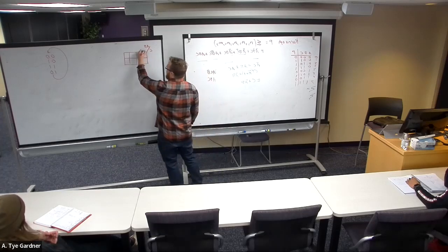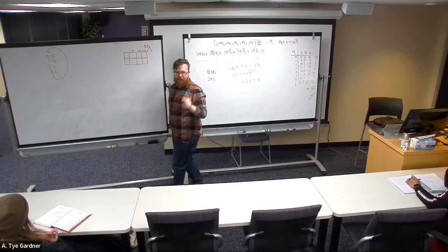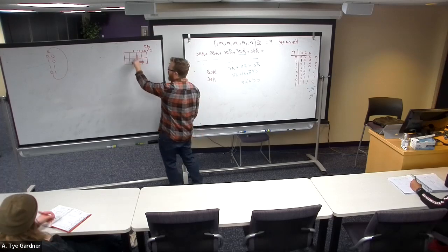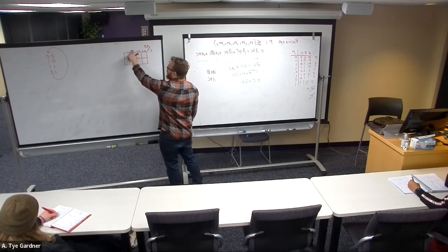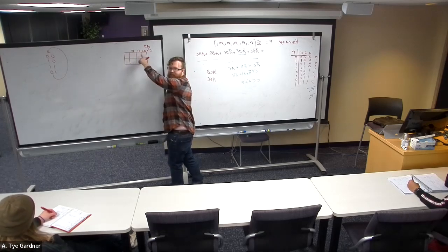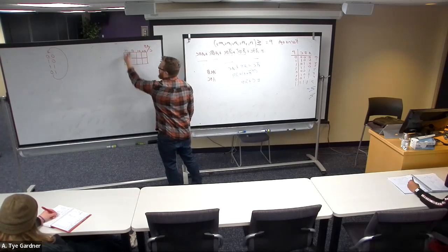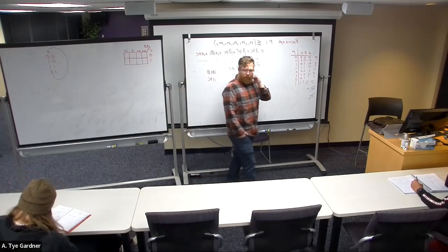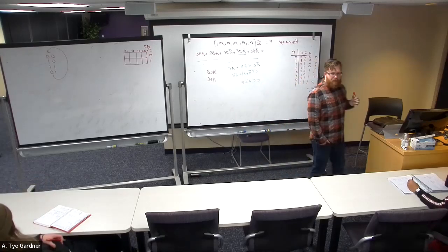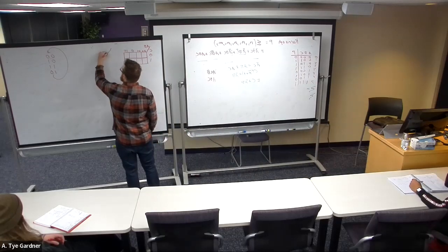So the way that this works is saying 0, 0, 0, 1, 1, 1, because we're going to Gray map. It is very, very important that you Gray map, or Gray code, your K-maps. If you flip this to 1, 0, now these two aren't logically adjacent, and it's hard to see logical adjacency. So 1, 1, 1, 0. This only has 2, 0, 1.